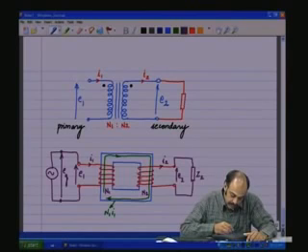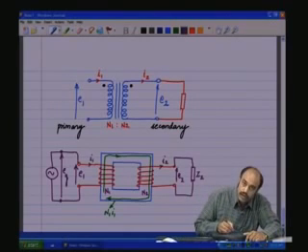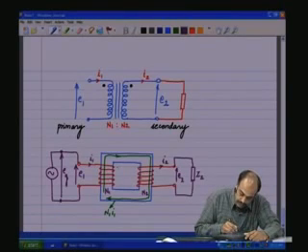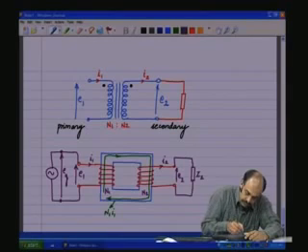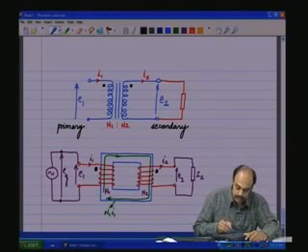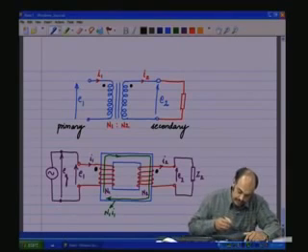Now this current is flowing through this coil, which is going to provide a cancelling motive force. So MMF is provided here, plus minus, let us say here at a given instant. Now a current flowing out of the dot, isn't it? Let me put the dot. The current is entering the dot, current is flowing out of the dot, is going to create a cancelling MMF.